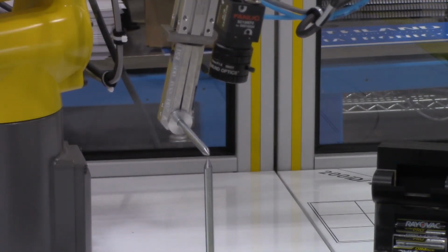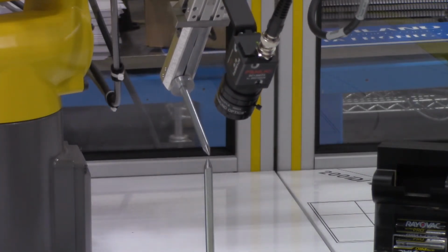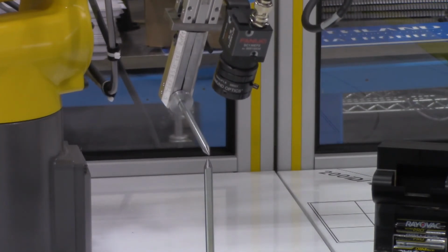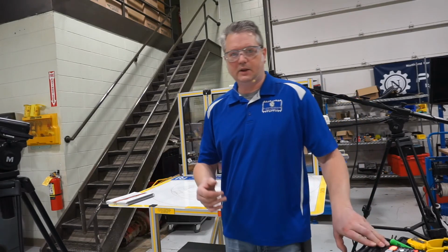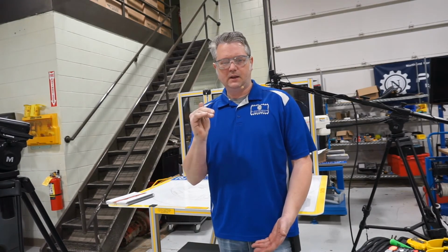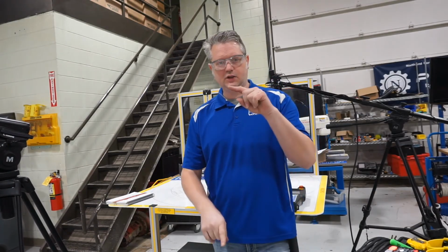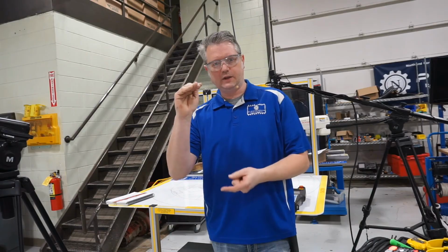So that's the 3-point method of programming in a new user tool. It basically, again, records the tool center point. So we'll have you guys practice those 2 different methods in the lab. You're going to be using both the direct entry method, and that's awesome especially if it's just a straight distance away where only the z-axis has changed. Then it's really easy. Just grab a ruler or a tape measure. How many millimeters is it from that end of the tool plate to the new tip? Put that in there as a direct entry method.